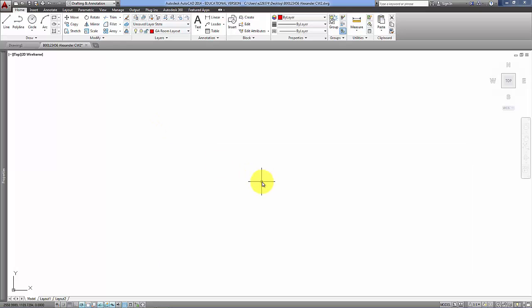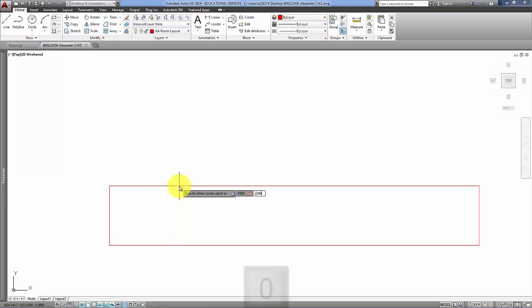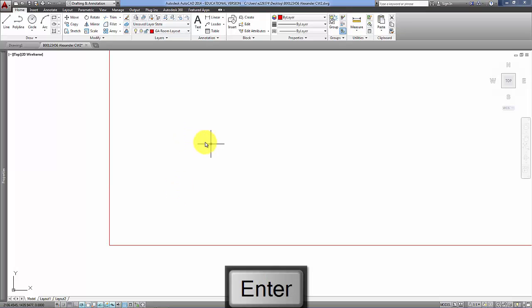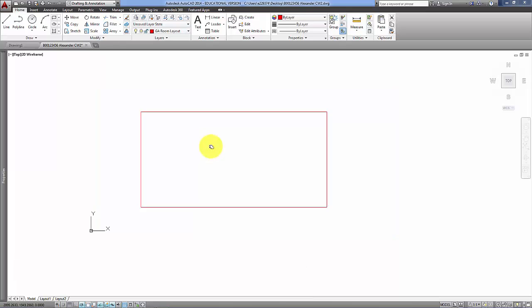So following the plan 3, the PDF, you can now begin to draw rectangles of the appropriate size. So the first one is 4500 by 2240. At this point you may need to double click with the middle mouse button to zoom out.